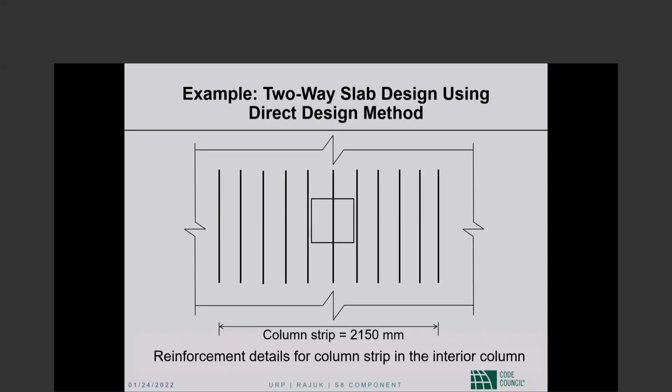Moving on. So in our country's slab design practice, we currently practice crank slab rebar. What? Crank slab rebar. I don't know what that is. That is, the main reinforcement is bent from bottom to top. Oh, in the slab.